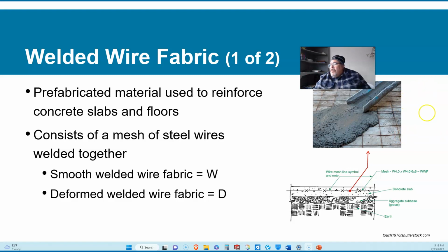So right now, this wire mesh is not doing the job that it would if it was laying inside the concrete, whereas here it's at the bottom level down here. So this wire mesh is not finished. It will be relocated. It'll be grabbed and pulled and raised in that pool of liquid concrete.